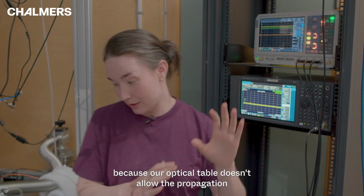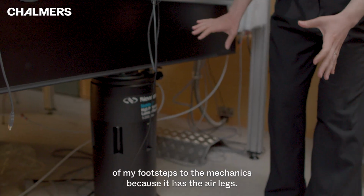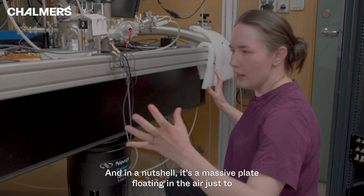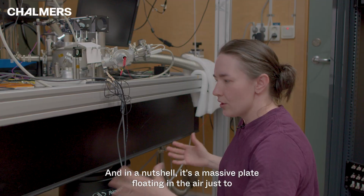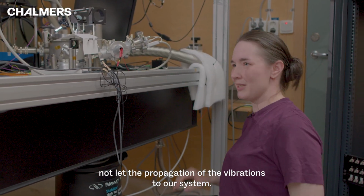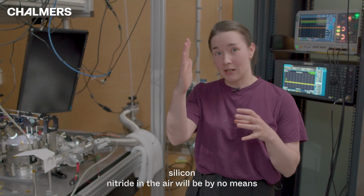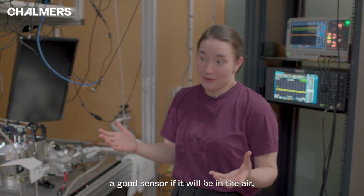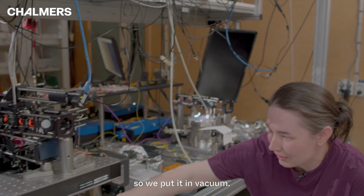And it's dumped because our optical table doesn't allow the propagation of my footsteps to the mechanics because it has the air legs. And in a nutshell, it's a massive plate floating in the air just to not let the propagation of the vibrations to our system. That's one thing. Another thing is that our 20 nanometer silicon nitride in the air will be by no means a good sensor if it will be in the air. So we put it in the vacuum.